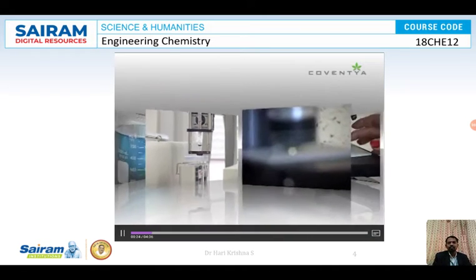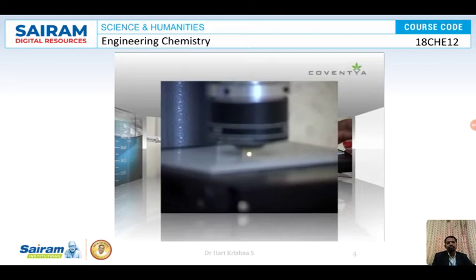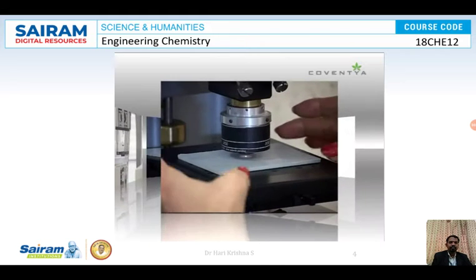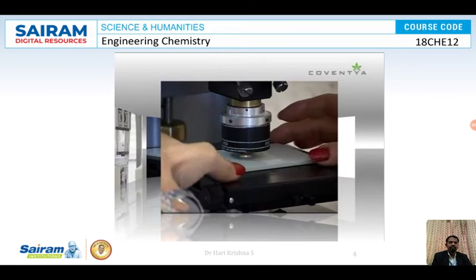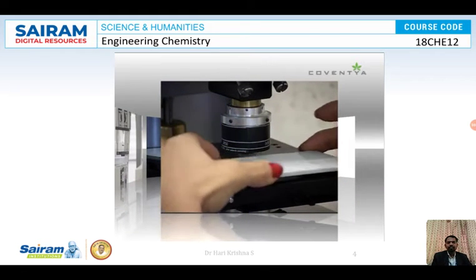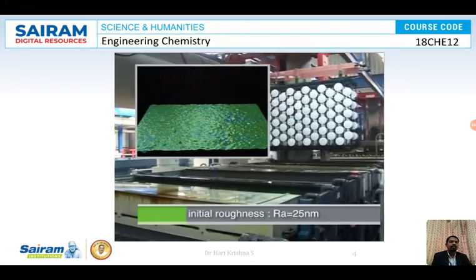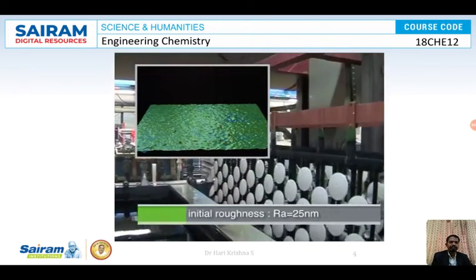Its characteristics for plastic parts. Attached to plating racks, bare parts are ready to be treated in a sequence of different chemicals. The first step of the sequence consists of cleaning residue from the plastic surface. Before processing, the average roughness of plastic is about 25 nanometers.